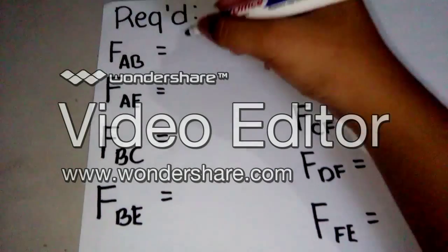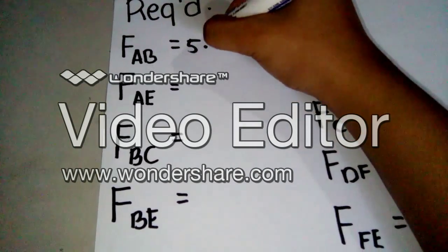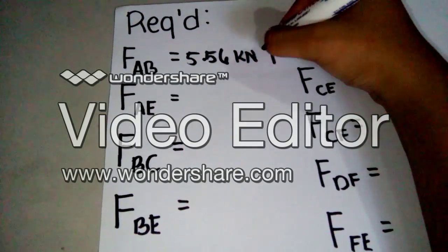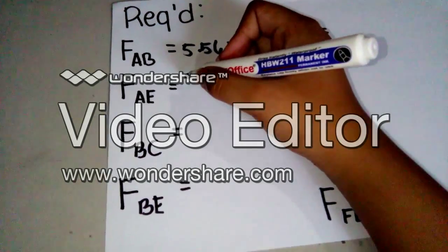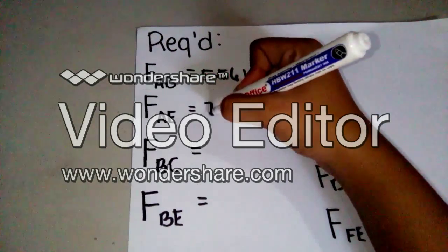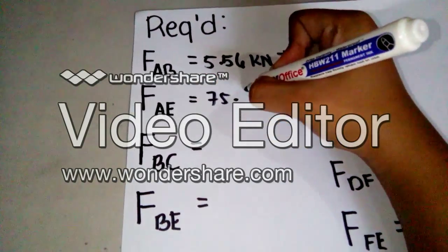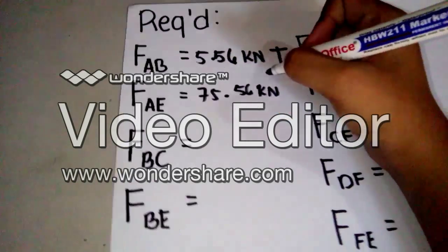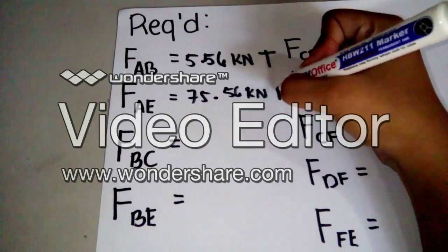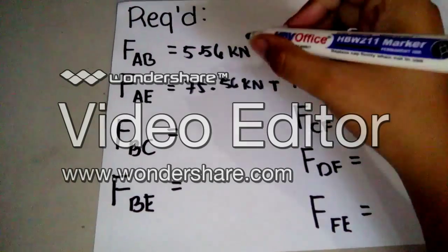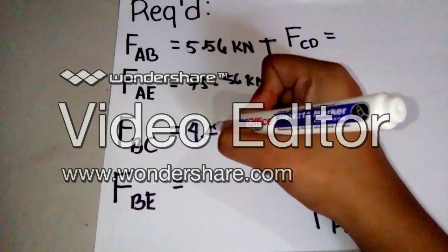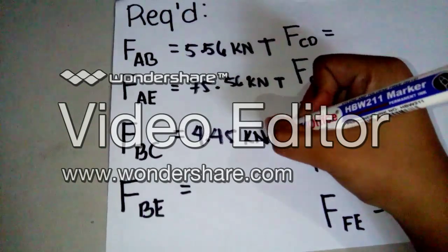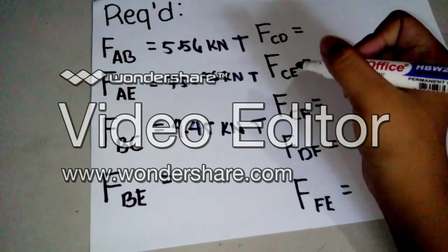So putting all solved values, we have FAB is equal to 5.56 kilonewton tension. FAE, 75.56 kilonewton tension. FBC is equal to 4.45 kilonewton tension.